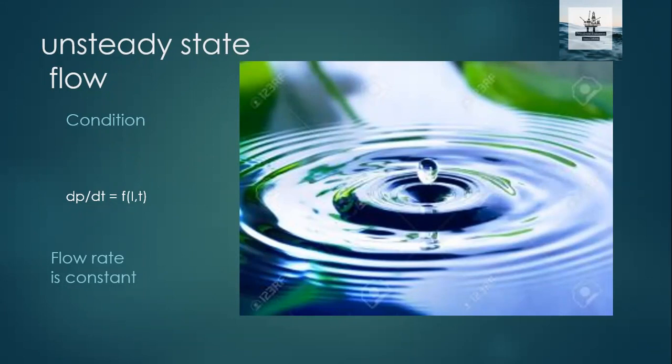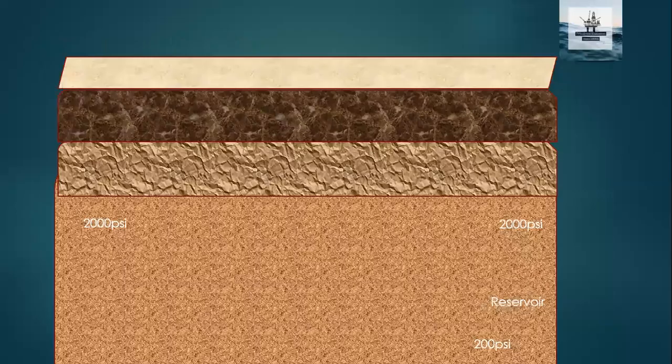Then after that, these ripples will start to saturate. Then this saturated time is considered to be pseudo steady state flow. Okay, this is how we can contextualize how unsteady state flow, steady state and pseudo steady state can be understood in a reservoir. Right now, I will try to simulate it directly with the reservoir to understand.